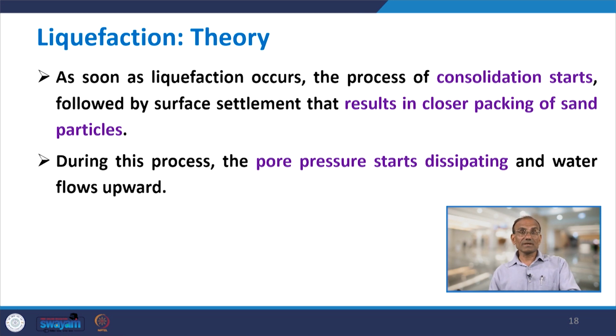Continue with the theory part. As soon as liquefaction occurs, the process of consolidation starts, and that will be followed by surface settlement that results in a closer packing of sand particles. So, that is another phenomenon. When the liquefaction occurs, some water will come on the top, but in the remaining part of the soil, there will be close packing of the particles, and its density may increase.